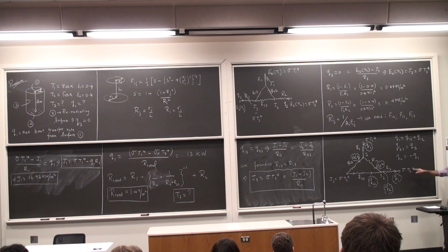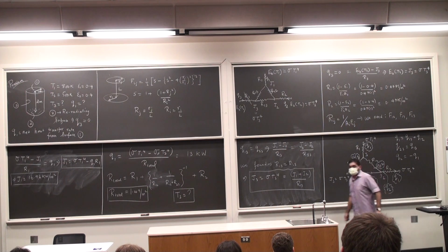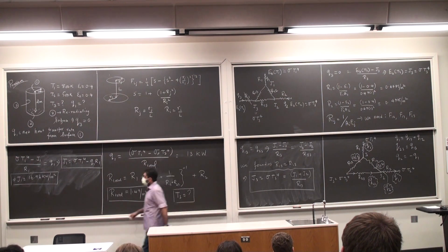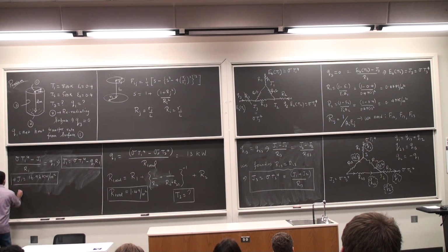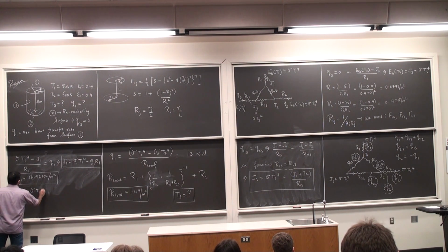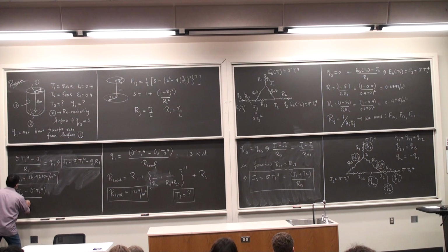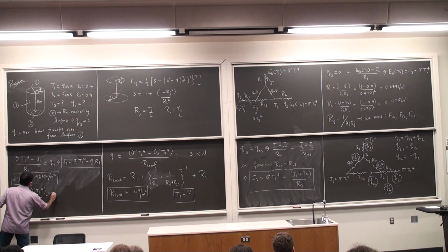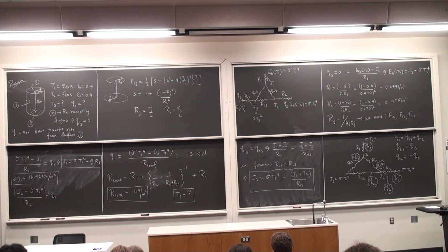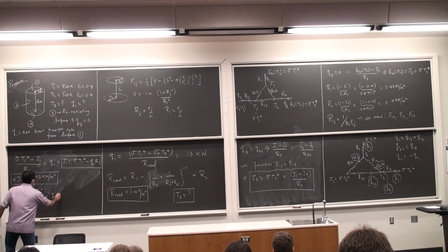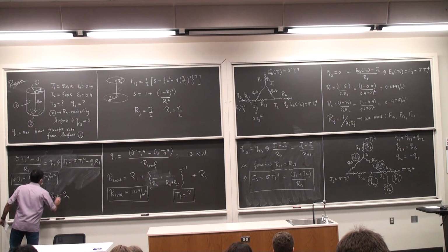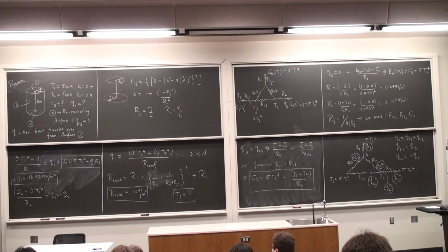So when you are writing the current as the potential difference divided by the resistance, you have to do the following for J2: J2 minus sigma T2 to the power 4 by R2 is equal to Q1, or this is equal to minus Q2, which I don't know, but I know Q1. So you can ignore this minus Q2 part, which tells me that J2 can be calculated.